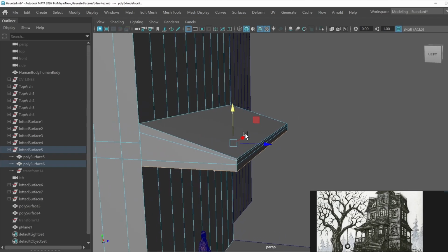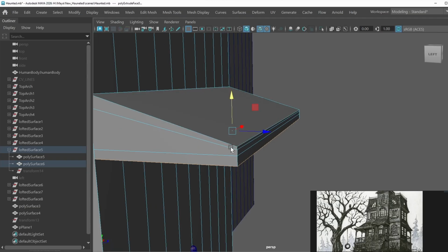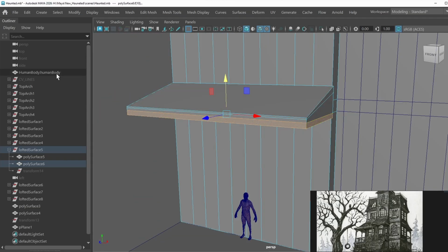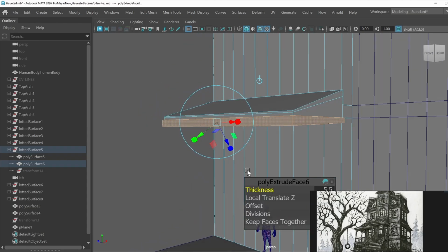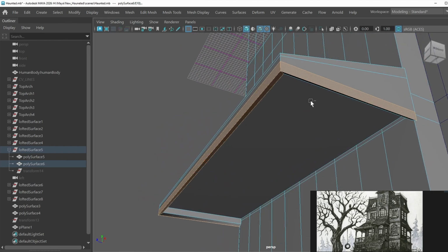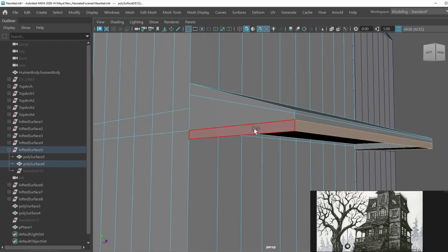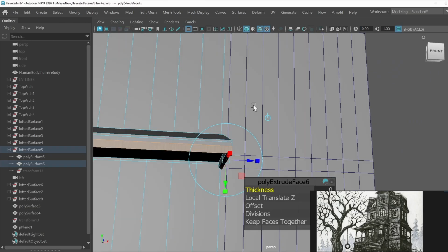And that allows me to bring these out, extrude out. I'm just kind of building definition here. Oh, I don't like that. Oh, it looks like I actually grabbed a face, which I do not want to grab. Let's try extrude again.